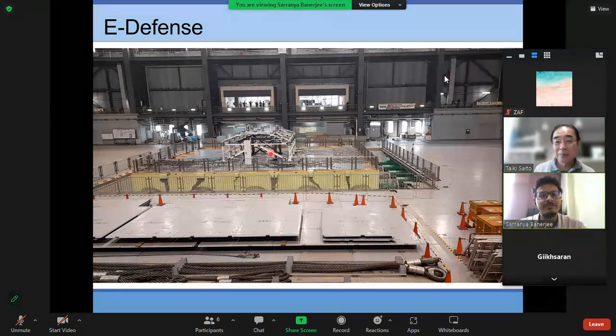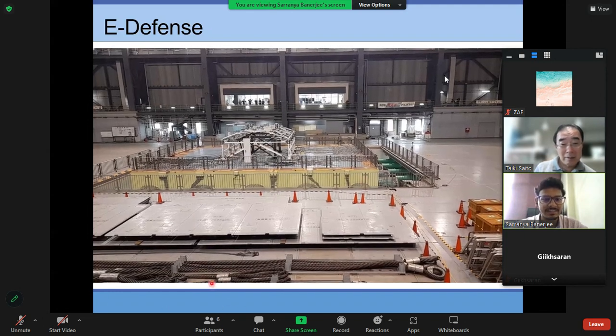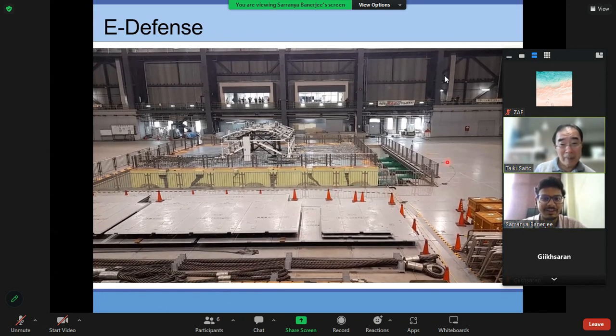Since it is only a one-story building, they are not very worried about the acceleration of the ground. But sometimes if the roof vibrates very much, then the roofing falls and that could create problems. So they wanted to control the vibration of the roof. They have two TMDs at these two parts, which are controlling the vibration of the roofs. And they also have friction dampers attached here. So they tested this, and this is the video of the vibration.